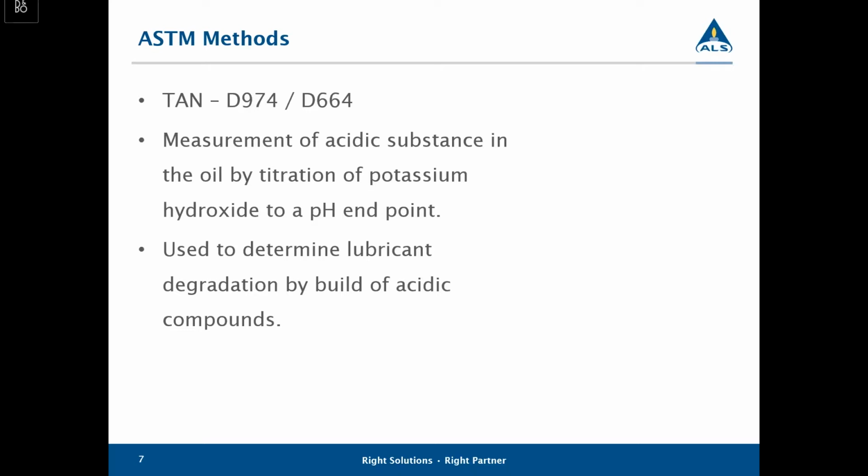You have nitration compounds occurring. You have nitrous oxides. You have all these acidic compounds that are getting into the oil. And what we're doing here is trying to measure how much of that acidic substance is getting into the oil, because that, along with being in presence of oxygen and heat, is going to accelerate the acidic buildup, and that acid is going to break down that oil.